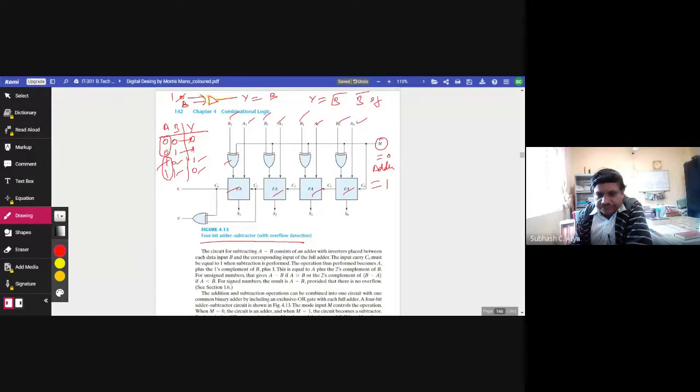In short form, if in the exclusive OR gate one of the inputs is 0, it will simply work as a pass gate. However, if it is 1, the exclusive OR gate will work as a NOT gate, or complement. Is it okay?